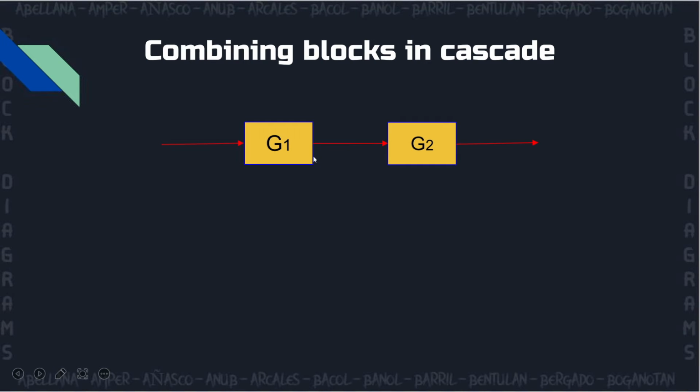So consider this block diagram with transfer functions G1 and G2 with input A. Since we know how to get the output of a block diagram, all we need to do is to multiply the transfer function from the input. The output in this part of the block diagram would be AG1, since we multiplied A and G1.